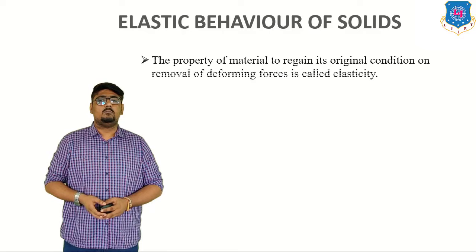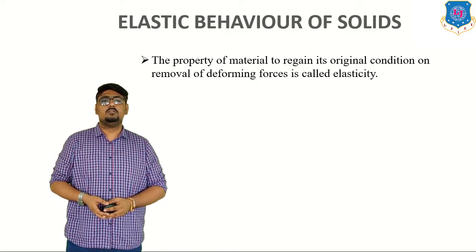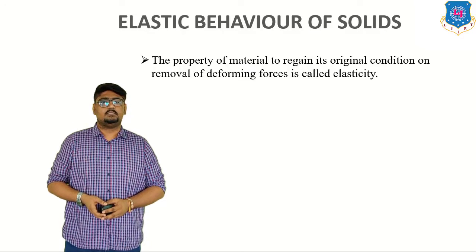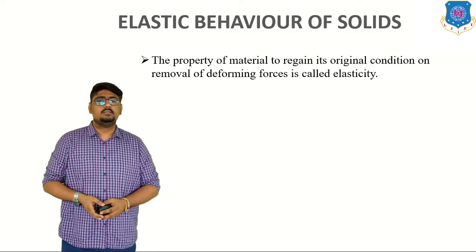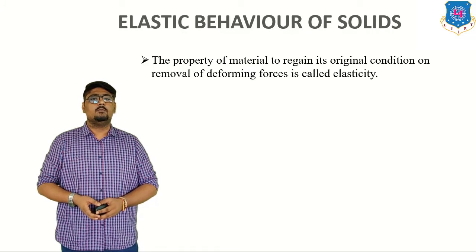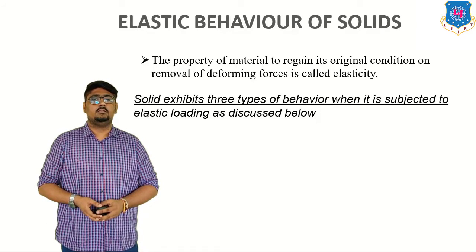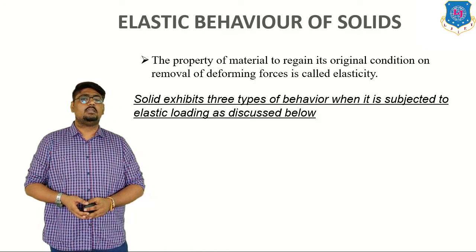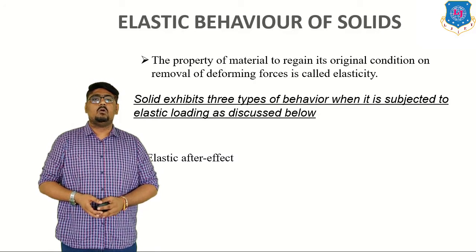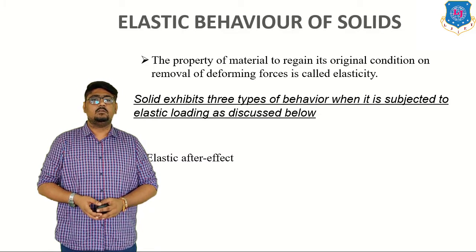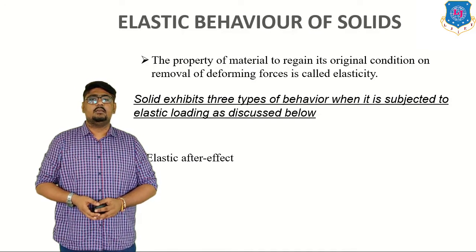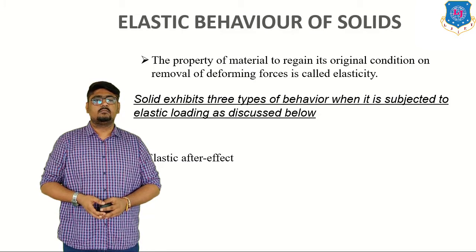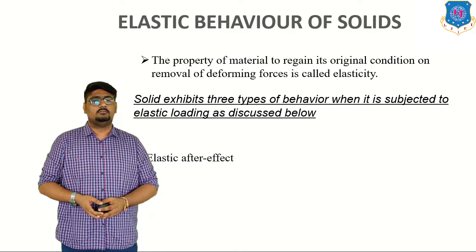The property of a material to regain its original condition on removal of deforming forces is known as elasticity. Solid exhibits three types of behavior when subjected to an elastic loading, as discussed below. The first one is elastic after effect. When a body is subjected to the tensile load, then it is expected that the body will gain its original position after unloading. This is the ideal condition.